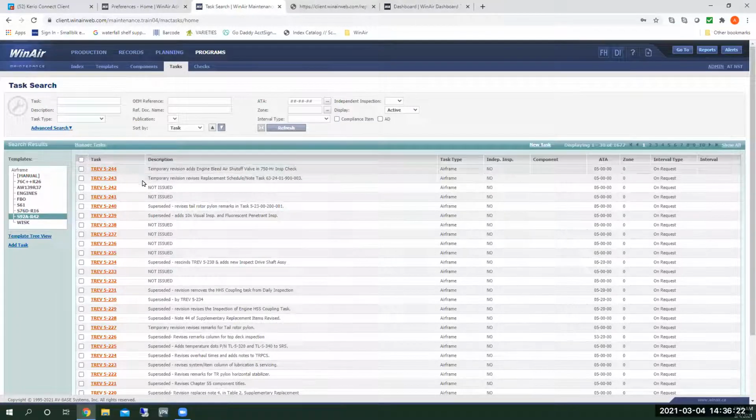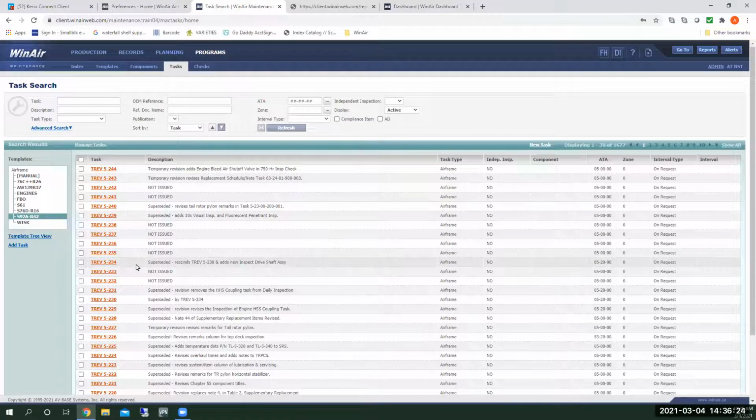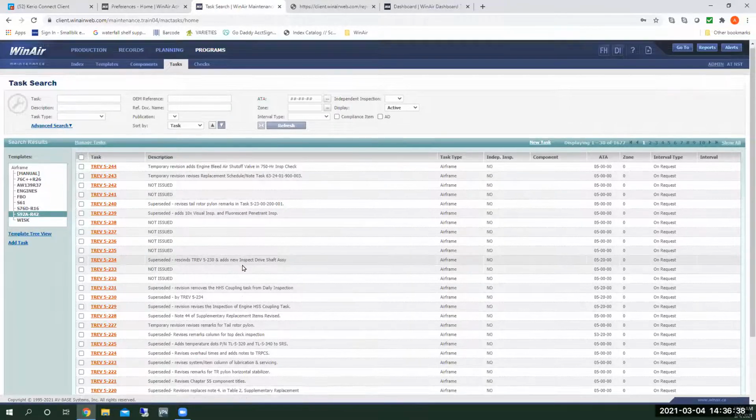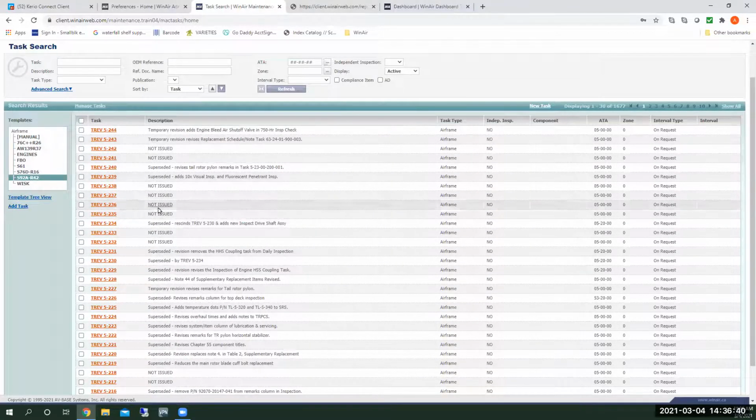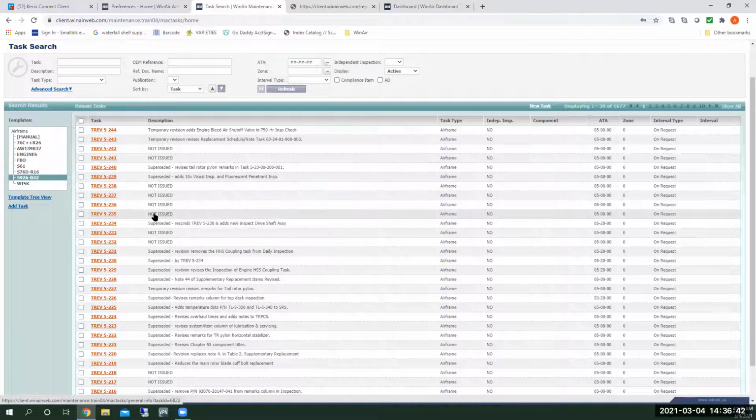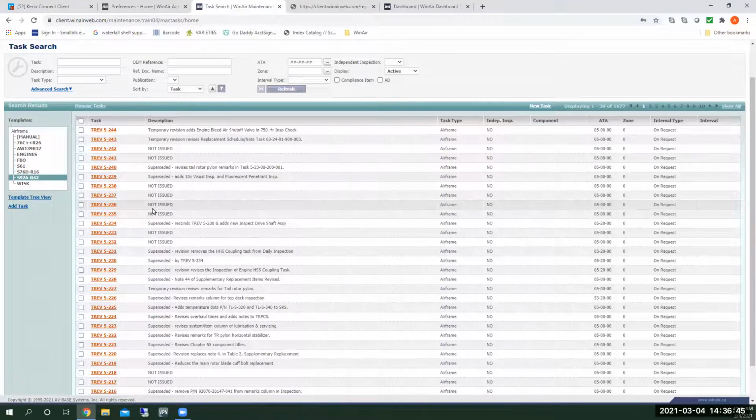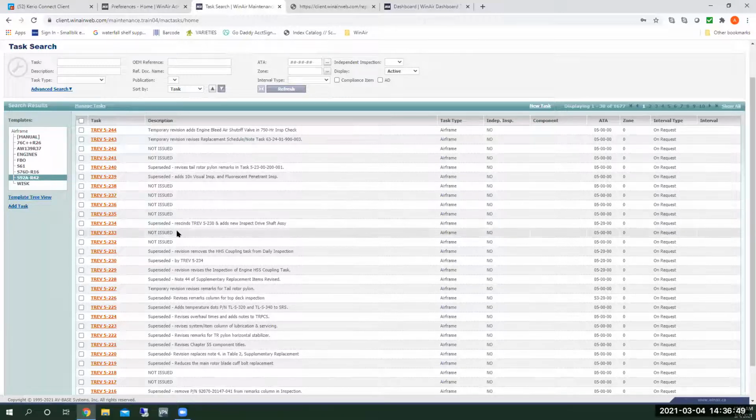So this is basically a digital copy of the requirements section of the maintenance manual, listing anything that's a scheduled maintenance check or a life limitation on a particular part that's installed to the aircraft. So you can think of these basically as a set of rubber stamps that creates a task card for the particular inspection that we are required to carry out.